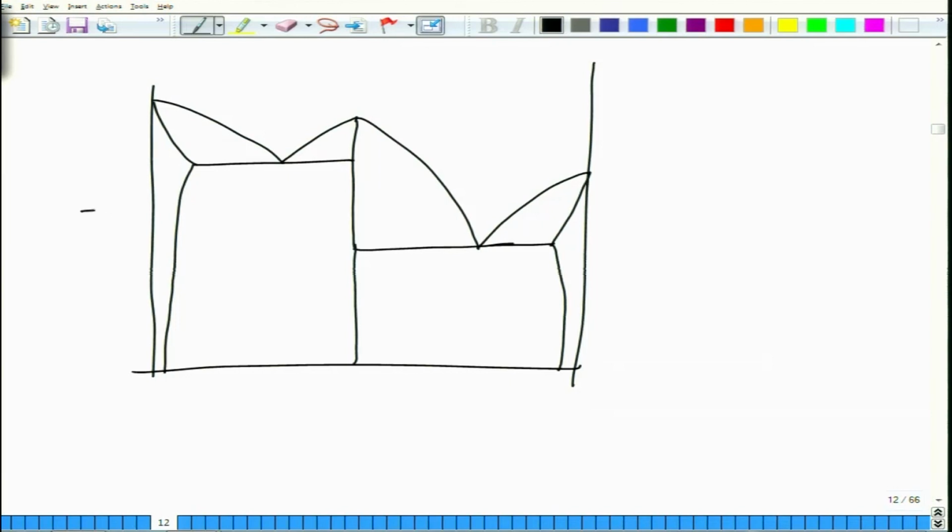So, this is an even more complex phase diagram. Here, this is all liquid. Here this is single phase region alpha, this is single phase region beta, in between you have a line compound gamma. So, this is the line compound gamma. On the right side you have liquid plus gamma, on the left side you have liquid plus beta, here you have again liquid plus gamma, liquid plus alpha, in between you have alpha plus gamma, and here you have beta plus gamma.